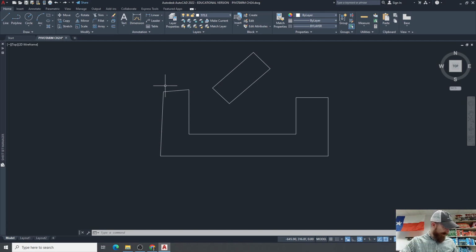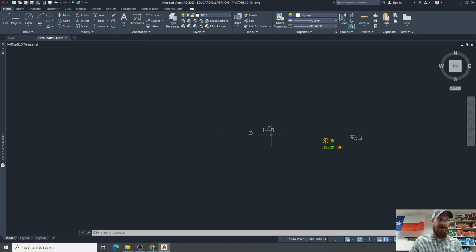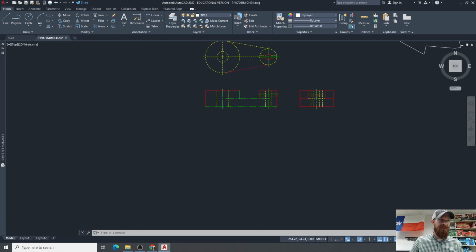First, the first source point is connected to, actually touches, the first destination point, causing a translation, a movement. Next, the vector defined by the first and second source point is aligned with the vector defined by the first and second destination point, causing a rotation. So basically this thing would move down into this corner and then rotate down to fit in where you want it to fit in. It's kind of a Tetris-y kind of thing. Okay, sorry, I've done a horrible job of explaining that one.